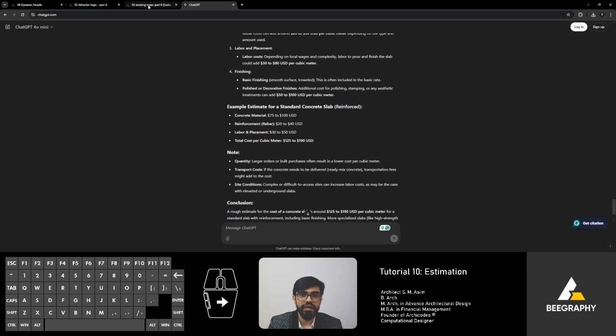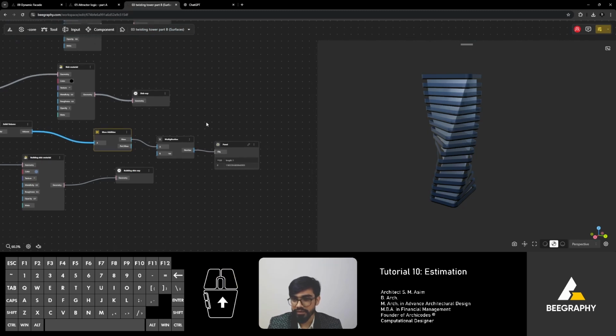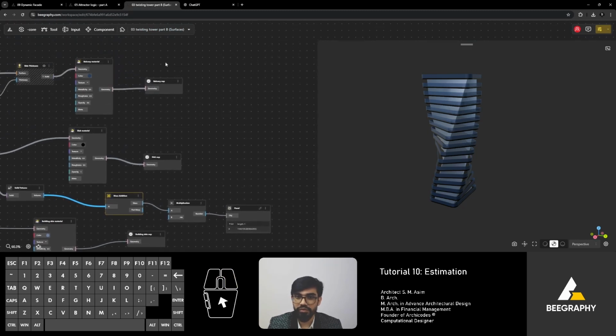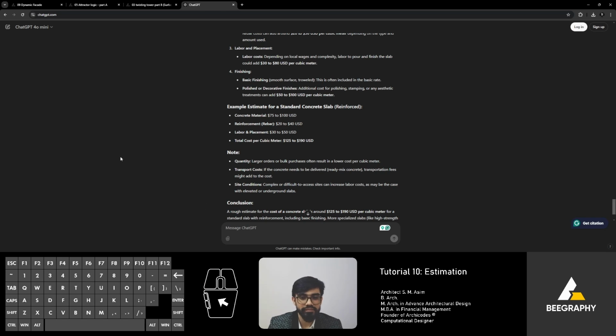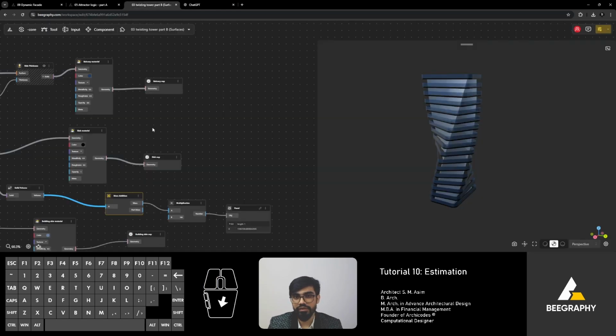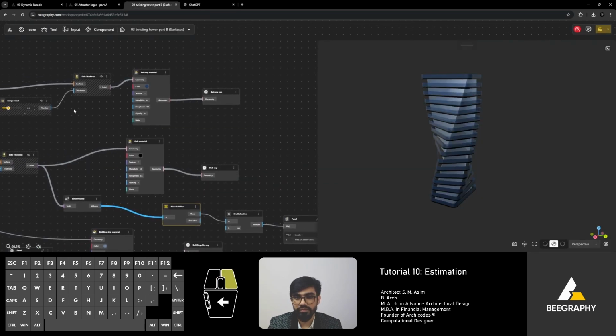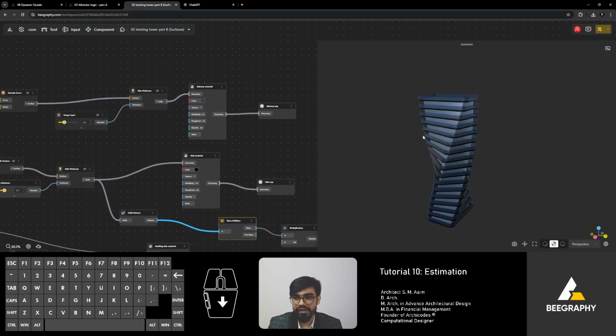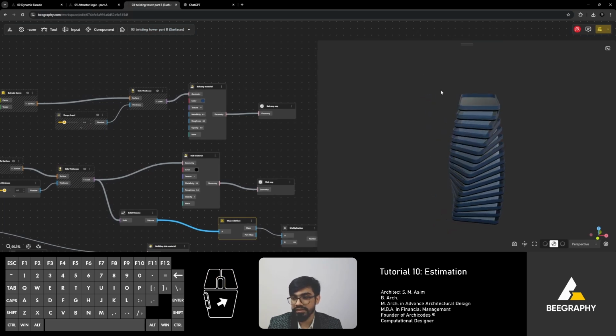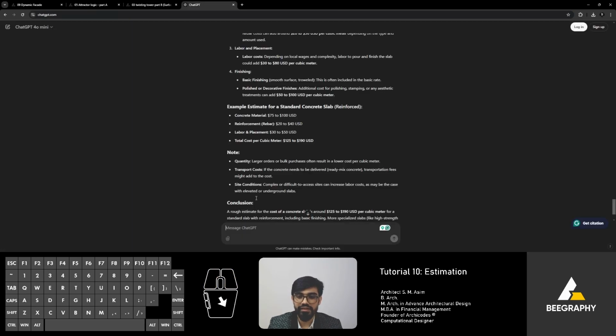Interesting. I was expecting it to be a lot more, but nice. And then we've got balcony walls. Now we can either do by volume or by running feet or even by the surface area. All three methods are valid. Let's do by volume.